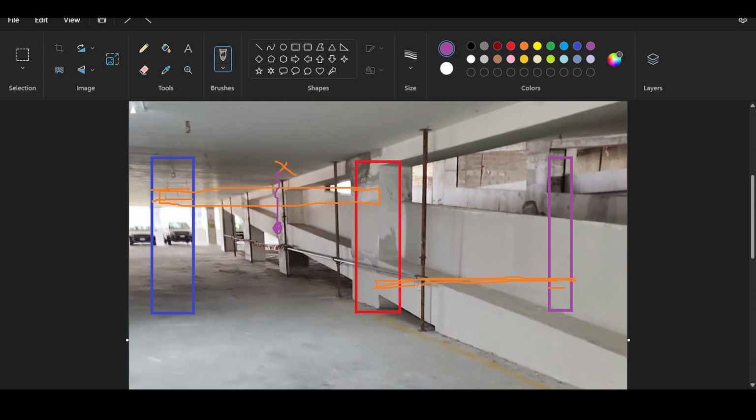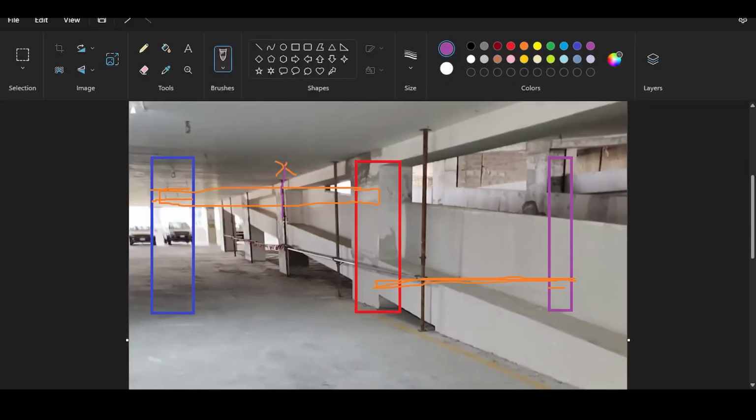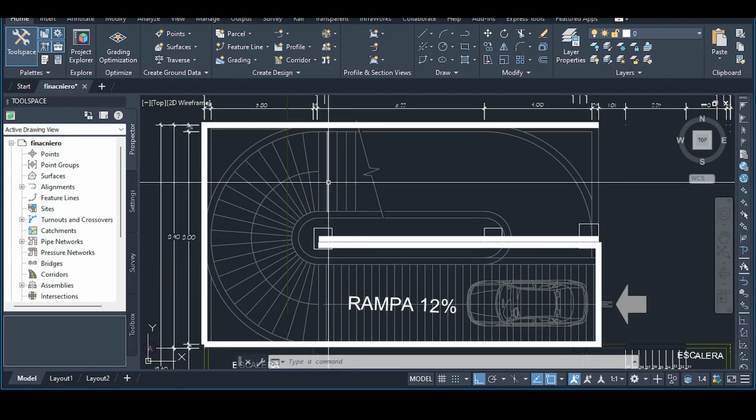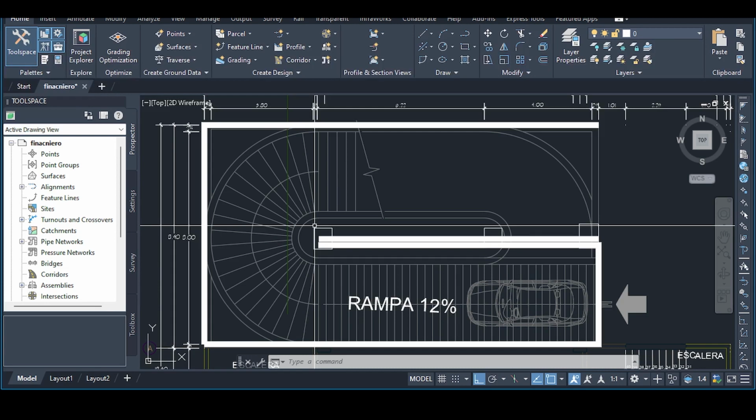If you have a spiral, then it would go down like this until it reaches this point. And then while it's rotating around the column, it's still going down. So it's spiraling down, and then it continues going down. Now, those are two approaches. I would choose the horizontal circle approach because it's simpler for modeling. And I already have a video for spirals, so you can check that out. But the most important point is to understand that when you do something, it has consequences in real life, in your construction. Now, there are advantages and disadvantages to both approaches.